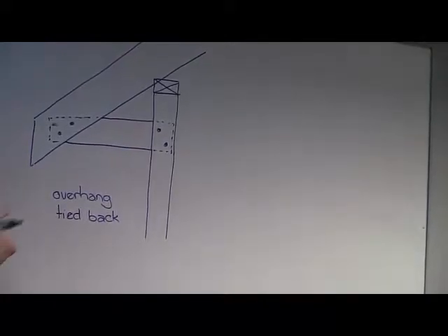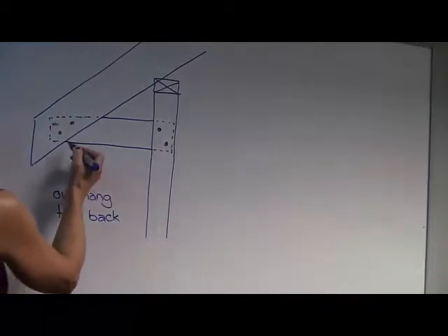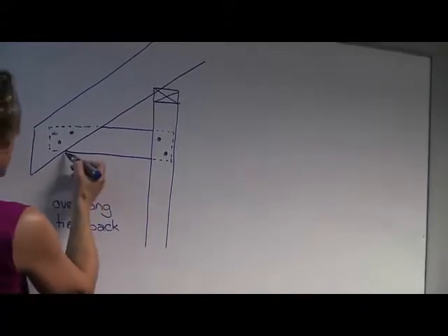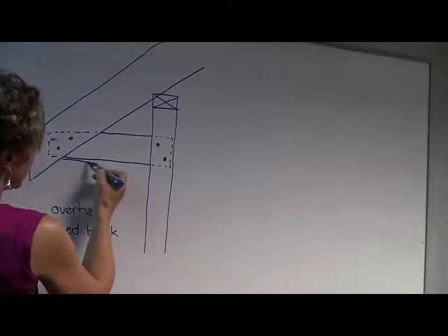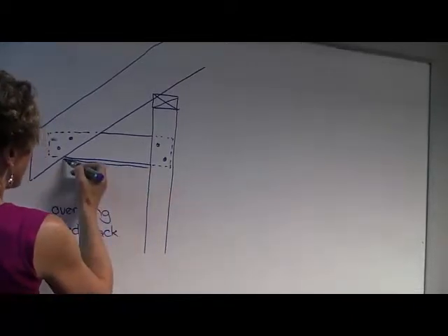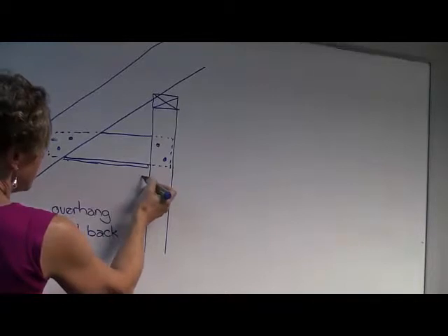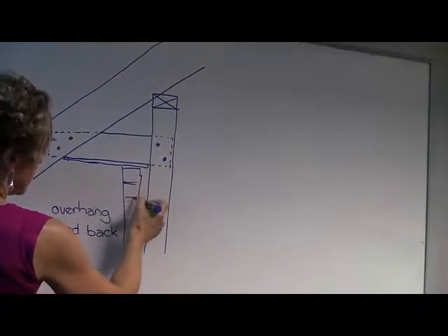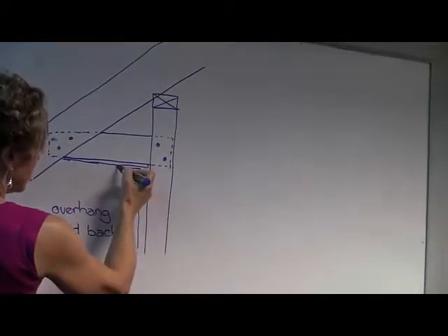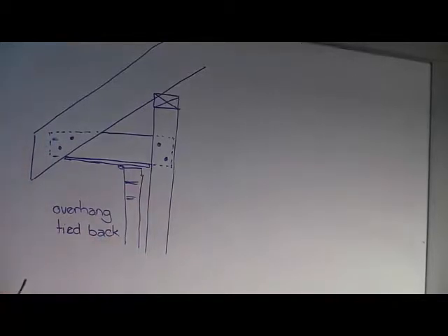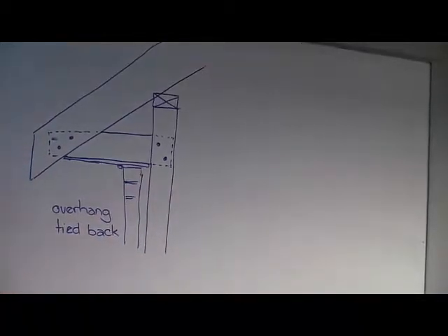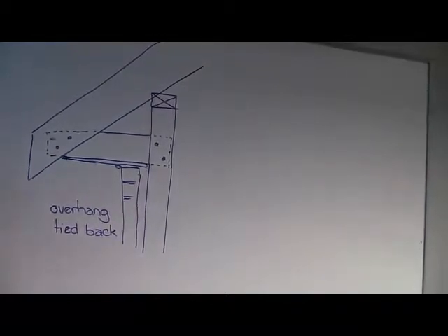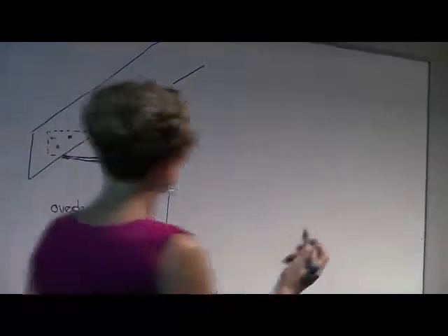All right? Now this is quite common, and you wouldn't see this tied back in a finished building because it would have some fibrous cement sheeting under there. Oh, there's your brickwork up to there, and you've probably got a little scotia there. So all you'll see is the underside of your eave. You'll see some lining. Okay, but that doesn't necessarily mean it's tied back, because sometimes